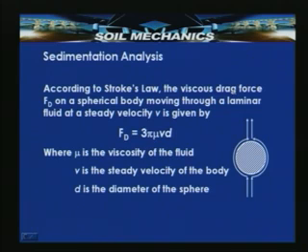Let us look into the theory behind the sedimentation analysis. As I said earlier, this sedimentation analysis is after Sir George Stokes, 1891. According to Stokes law, the viscous drag force Fd on a spherical body moving through a laminar fluid at a steady state velocity V is given by Fd = 3 pi mu V d.